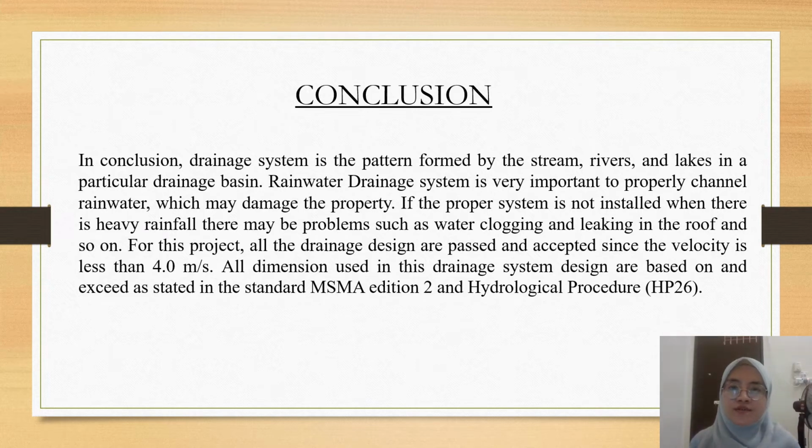So for this project, all the drainage designs are passed and accepted since the velocity is less than 4 meters per second, and all dimensions have been used by referring to the standard MASMA second edition and hydrological procedure, which is HP26.